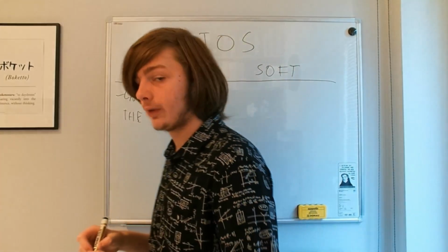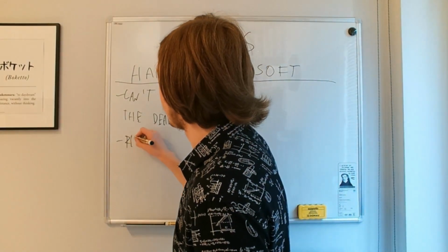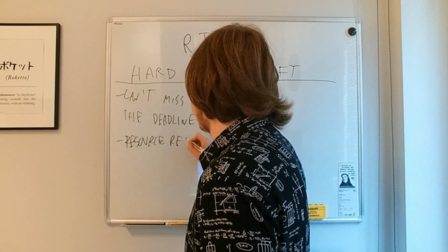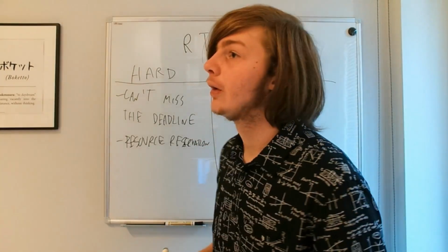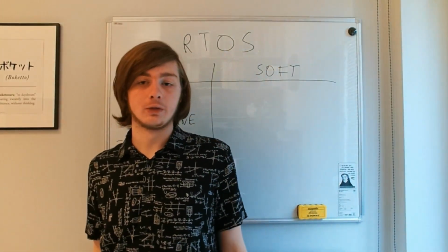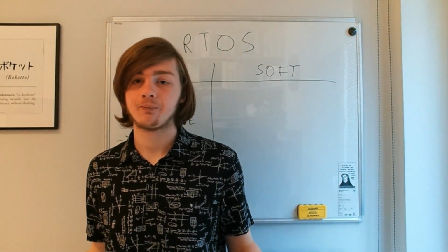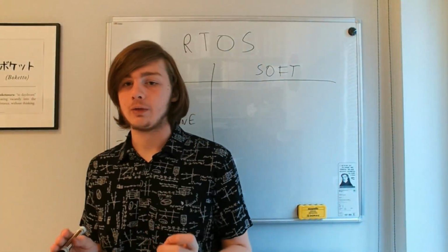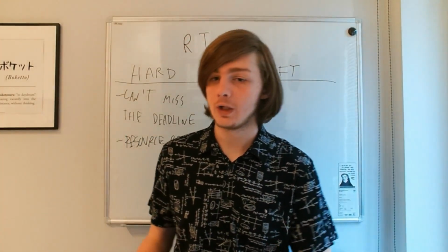It is absolutely forbidden, and it has to use techniques such as resource reservation. And the idea of resource reservation is that if the RTOS is not 100% certain that it can execute the process before the deadline, it just doesn't do it. Because it absolutely has to do this before the deadline. So an example would be